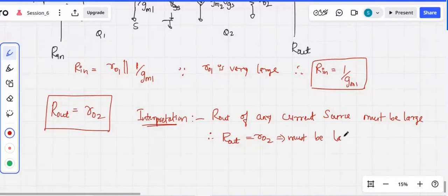And we have already seen through the simulation how we calculate the finite output resistance. So henceforth, if you calculate any MOSFET's small signal R0, which is the finite output resistance, that itself can be considered as the output resistance if I am using that MOSFET to build a current source. Our design started that way. We started with a simple MOSFET, characterizing its drain current with respect to VGS and VDS, plotted the graphs, took the derivative, and figured out the finite output resistance, which is my small R0. From this exercise we can summarize that the small R0 can be utilized as the output resistance whenever we use this MOSFET in building current sources. So this is basically R out, and it should be very, very large.